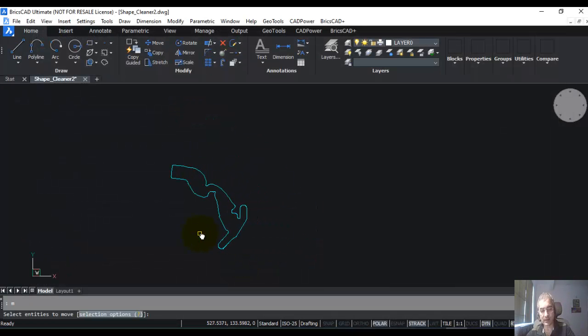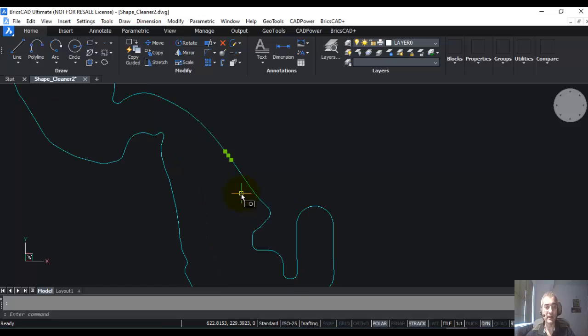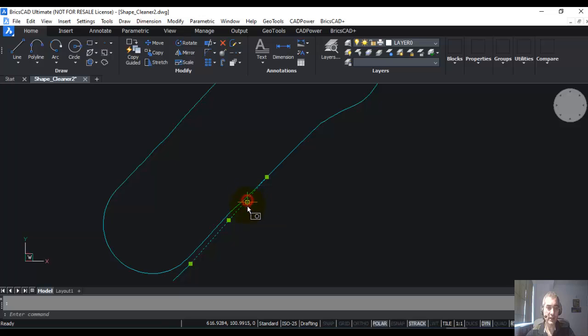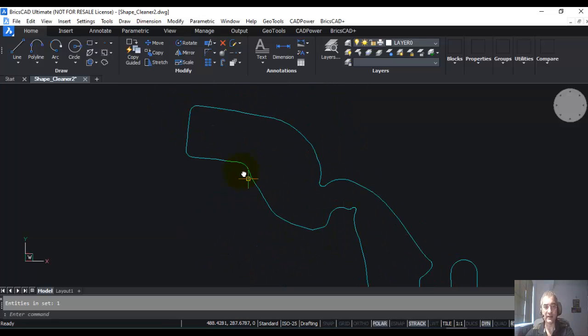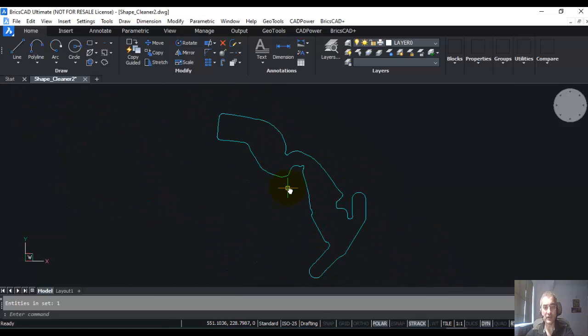Which means I can just type move previous and I can visually see what those duplicate objects are. So these objects are duplicated over these. So I can safely delete them now. Now what I am left with are lines and arcs without any duplication. Now it is always a good idea to just quickly visually check and remove obvious errors like undershoots or overshoots or mistakes that are there in the translation. Now the rest looks clean to me, so I'm going to proceed to the next step.